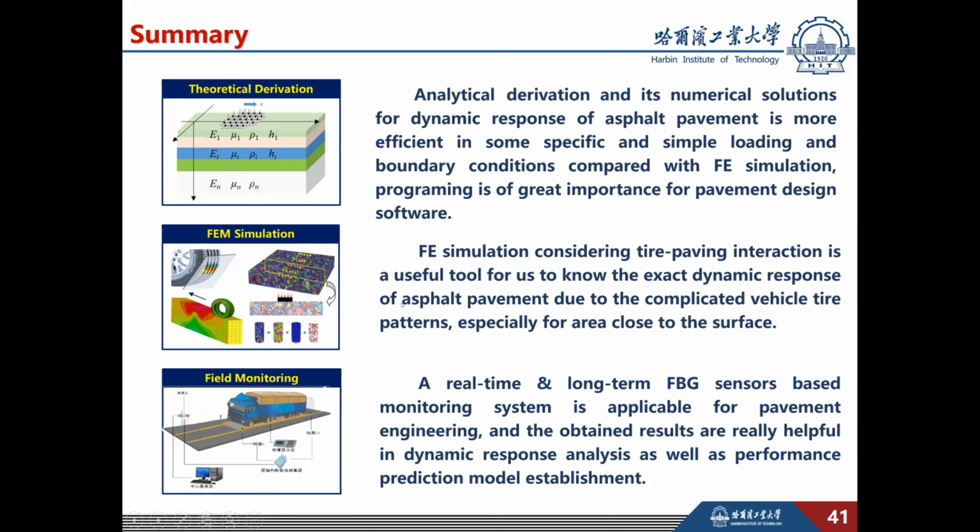And finite element simulation considering pavement interactions is a useful tool for us to know the exact dynamic response of asphalt pavement, because we can consider some complicated vertical vehicle tire patterns. And a real-time and long-term FBG sensor based monitoring system is applicable for pavement engineering.